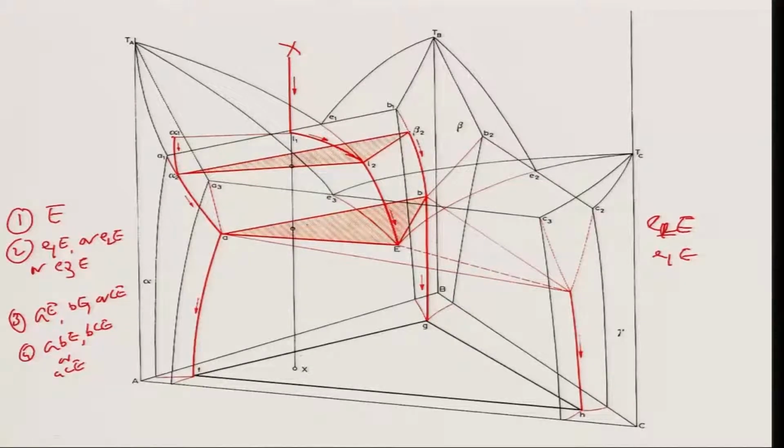Okay. Now, if you have a composition sitting on ABE, or BCE, or ACE, it does not matter. Here it is showing ABE. What will happen? This will lead to formation of again alpha and beta simultaneously, followed by formation of Ternary eutectic. So, there is no need of discussing that. Now, further to this, we can also have different variations of Ternary eutectic, right.